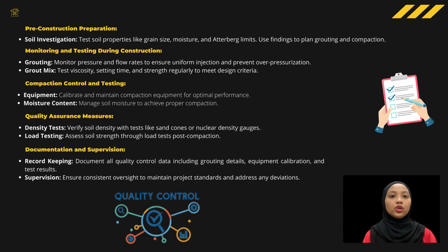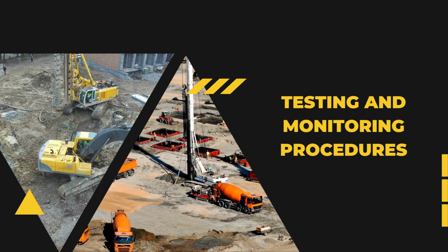Lastly, do the documentation and supervision. For record keeping, document all quality control data including grouting details, equipment calibration, and test results. Next is supervision, to ensure consistent oversight to maintain project standards and address any deviation.